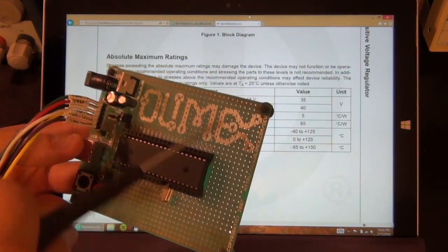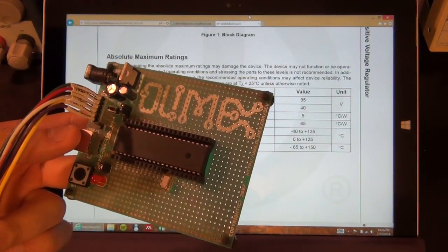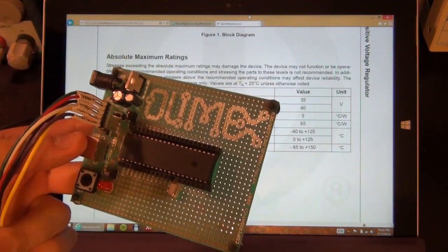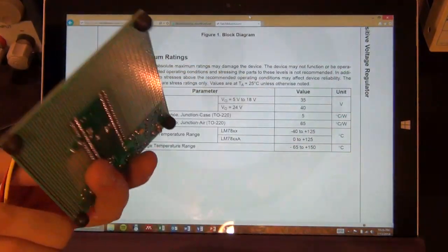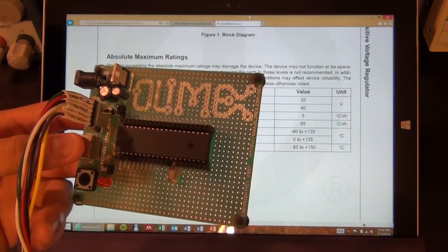What we're going to do is isolate the VDD of this guy and power it directly through the computer's 5 volt. We're going to share the ground of this and the power supply and the NeoPixels, and everything's going to work out nicely. So I'll connect it all up together, and let's look at the code next.